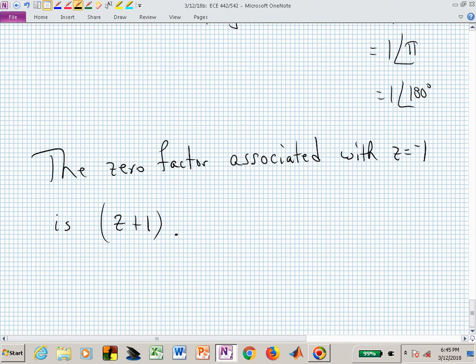Now, I gave you some additional material in an email today, didn't I? It's at the bottom of Unit 4. It says hints for solving these relationships, and it's really trying to justify why your answer might be different than MATLAB. MATLAB maps one fewer 0 at infinity to this z plus 1 factor. Maybe the constants aren't the same, but the gain of the overall transfer function better be the same at the same frequency.